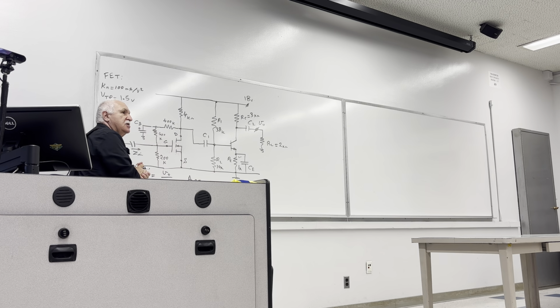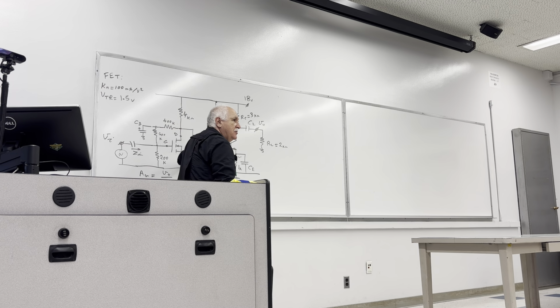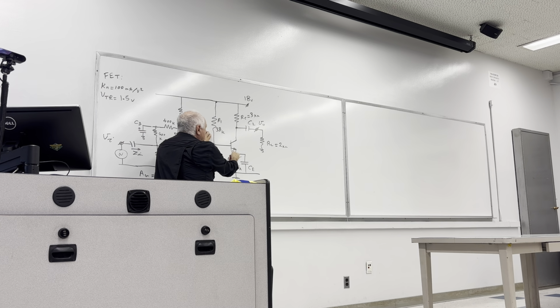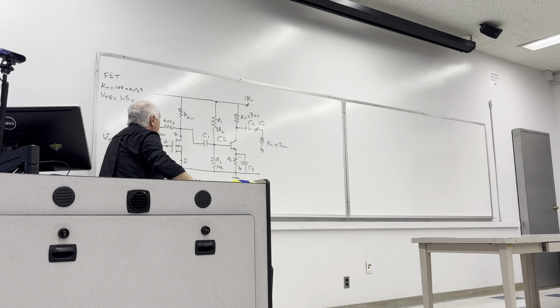But first thing is, number 1, DC analysis. How do we go about analyzing the DC in here? Okay, so how do we do that? For DC analysis, this is done stage by stage. Because the capacitor is there, you put the capacitors to open, this one to open, that one to open, you recognize what is that one. This is the good old CE amplifier, straight CE amplifier. We will do the DC analysis of that one, then we will perform the DC analysis of this one.